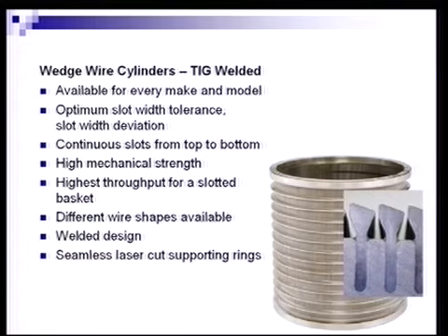The trick to this basket is that it's made seamlessly. It is not rolled. The support rings are cut out by a laser, and all the dental work is cut into it, and then it is assembled in a comb arrangement. The wires are hand fit into each slot, and then the flanges are put on and it's tilted over and TIG welded on both sides of the support rings.